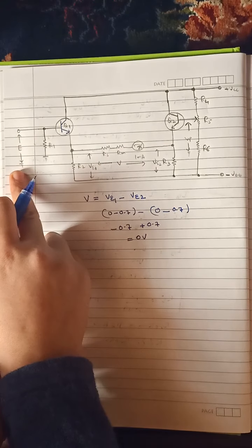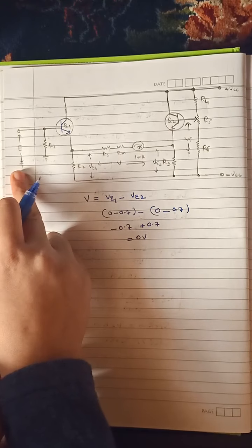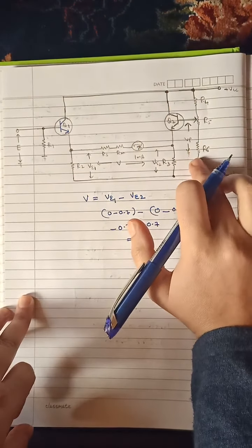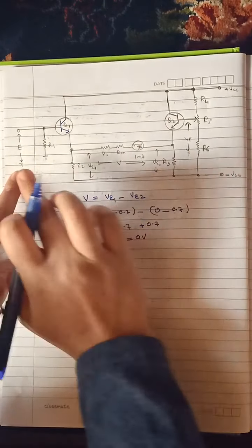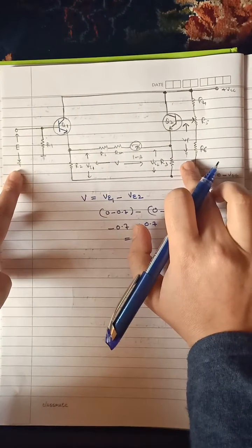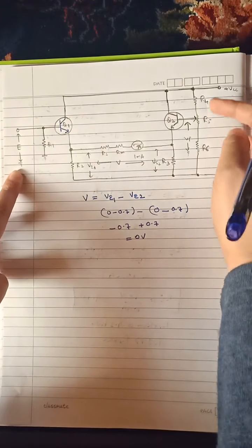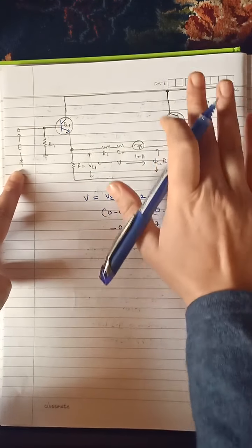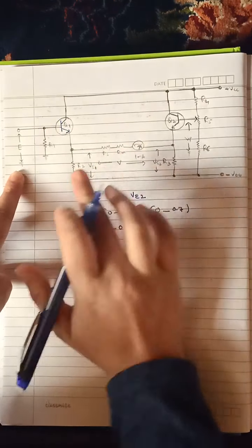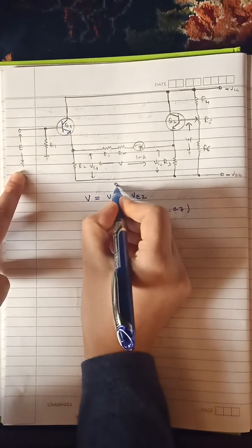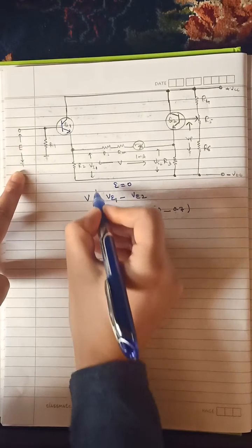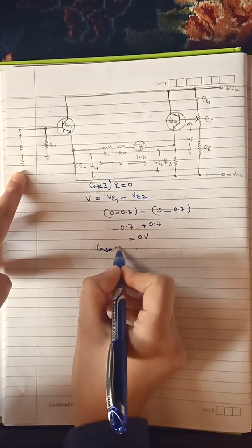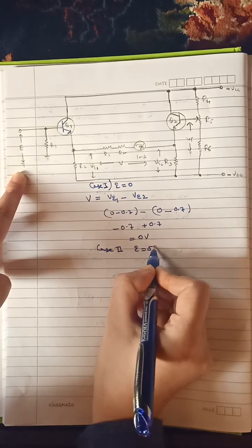Now say if E is equal to 5 volts, now we don't have to touch this part of the circuit. We have already connected it for when earlier this voltage was 0, we have already adjusted this voltage divider circuit and made this VP equal to 0. Now we do not need to change this part of the circuit. This was the case when E was equal to 0, this was say case first. Now we have case second where say E is equal to 5 volts.